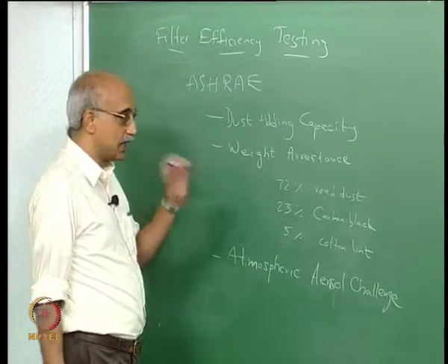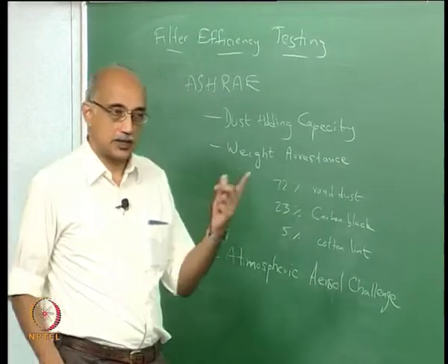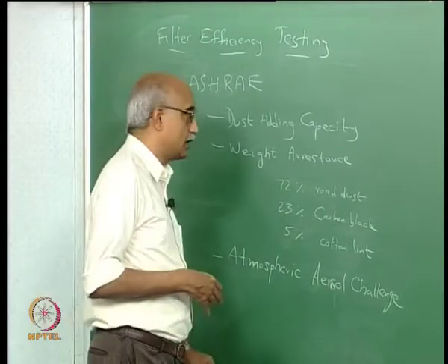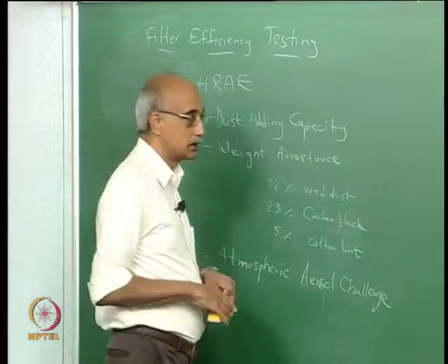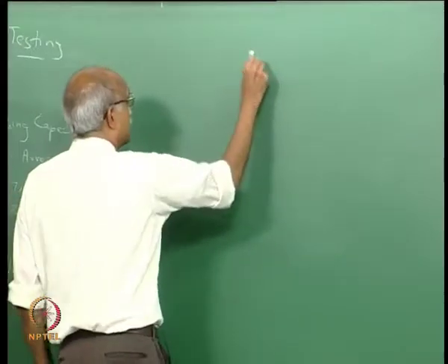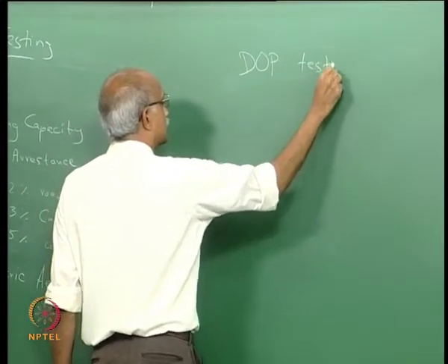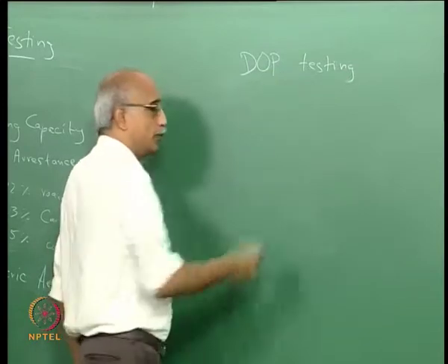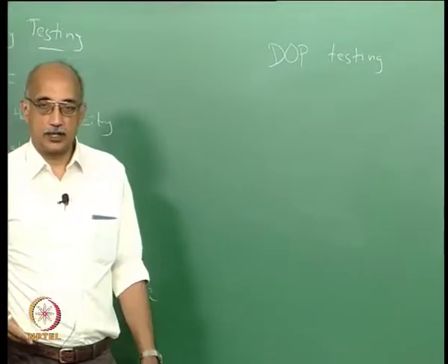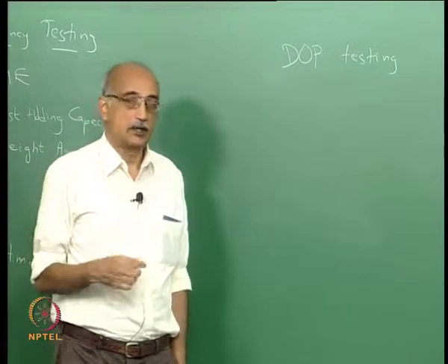But if you want to challenge the filter in the MPPS size range that I talked about earlier, then you have to specially formulate that material. And that method is known as DOP testing. DOP stands for dioctyl phthalate.